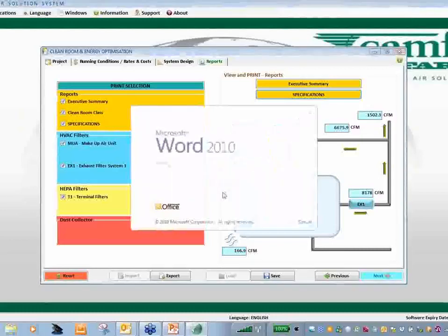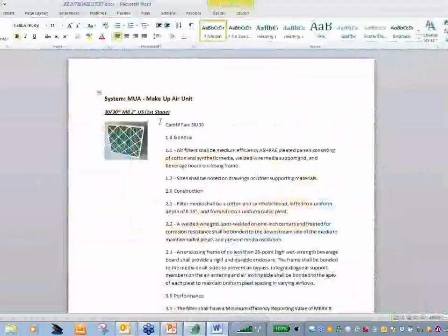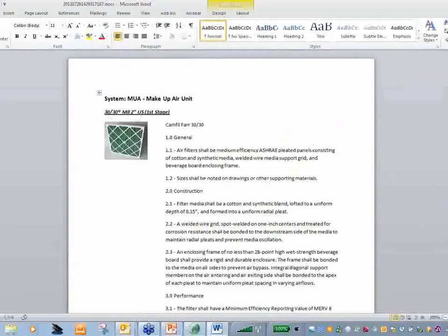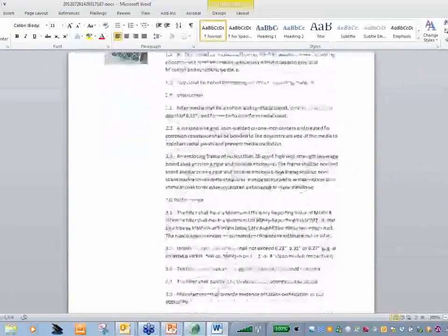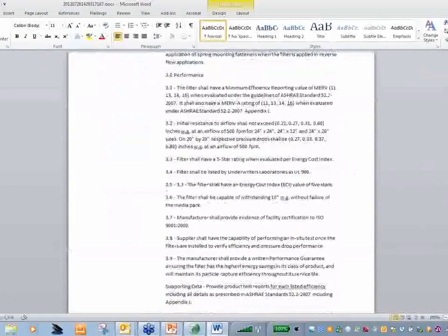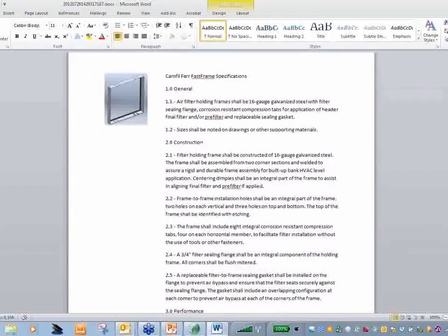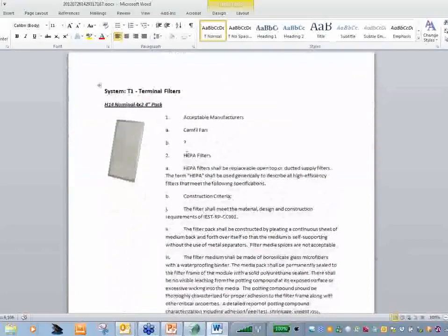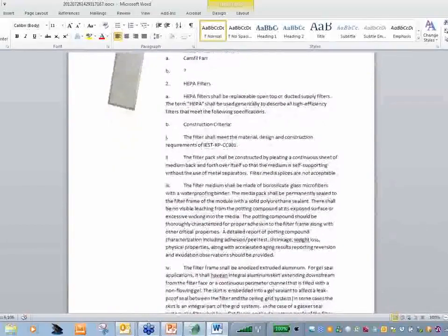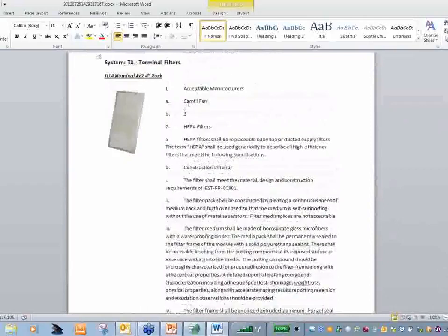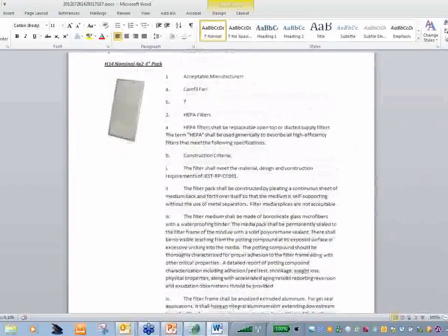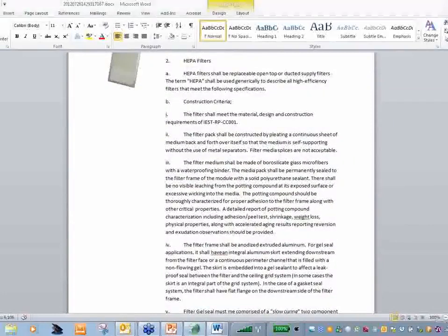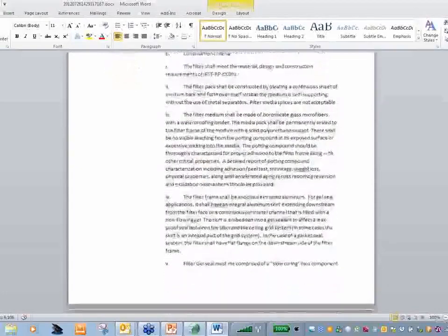And it's in Word. And basically, we start from what we selected for the makeup air. We had that pre-filter. We had the Durafilter secondary filter. We had the fast frame. We had 2 of them, so it's going to give it to you twice. We selected the Megalamp panel for the pharmaceutical housing, and here you get a very detailed spec, and we understand you've got to put in, brand X as a consulting engineer in some cases, but you're going to get a spec to the latest norms. I think that's the most important thing.